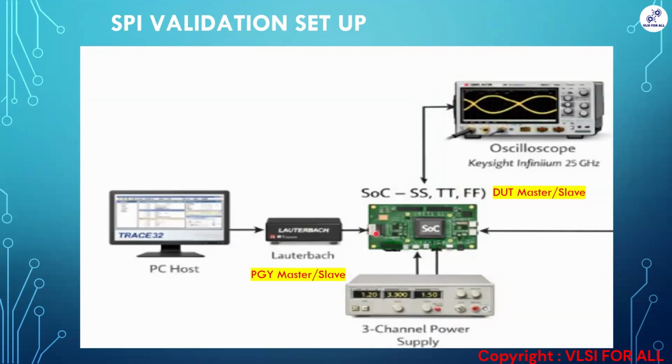In the 20-pin JTAG, on the backside of that, we will be doing some soldering to make sure that 4 pins are connected to the 4 channels of the oscilloscope of high bandwidth of 25 gigahertz. And we'll be having the power supply as usual. Using banana cables, we'll keep that power supply. And we will see the corresponding signals in the oscilloscope.